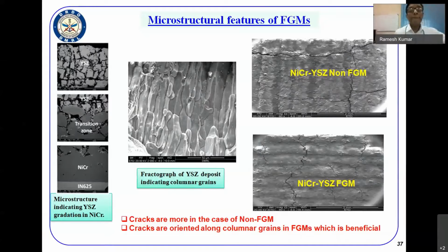If we see this component, in the conventional process it is an assembly of 2 parts. There is an injector and there is an O-ring here. These parts were complex machined from a cylindrical block using CNC machines. Part 2, the O-ring, was welded to part 1 through electron beam welding, a very costly process. And there were 3 injectors made.